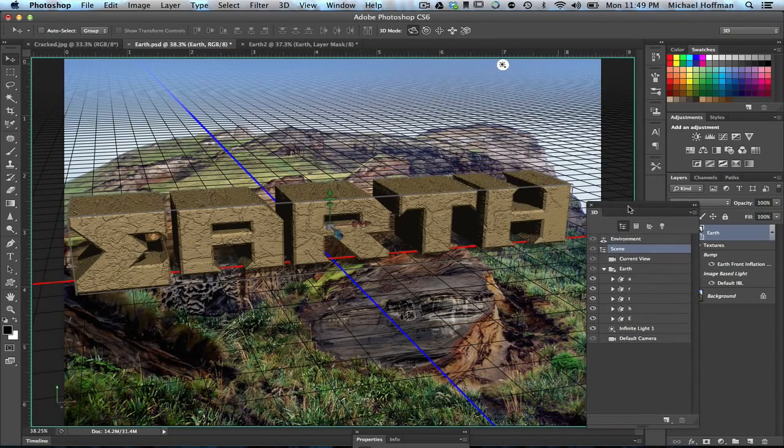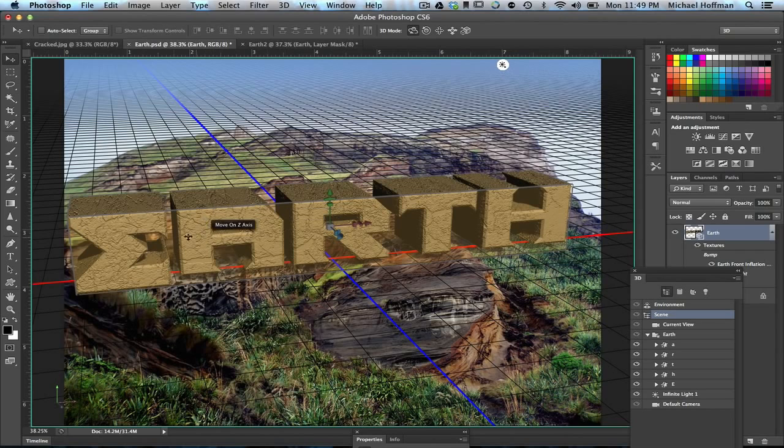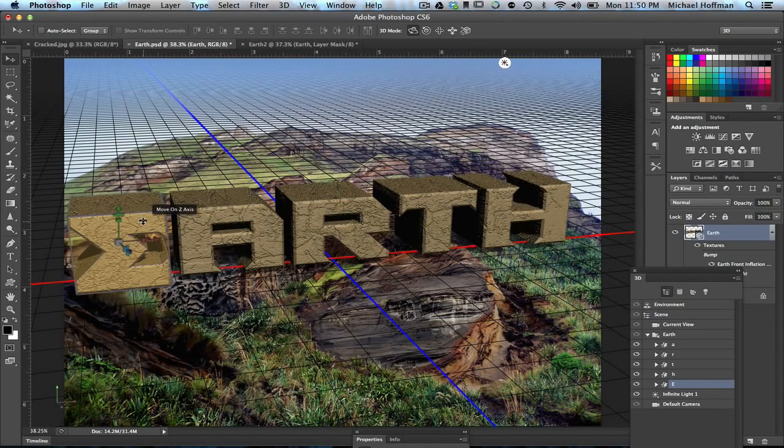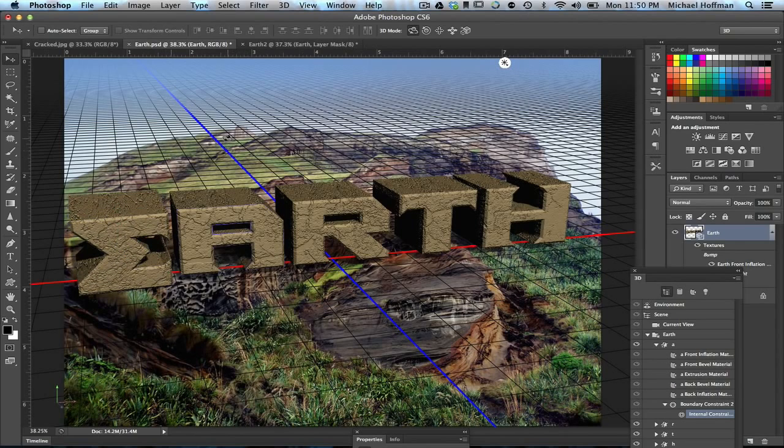So that means we can actually click on each individual one of these, and we can move it around independently of the others. So we'll just click, choose, and reposition and get these things set up the way that we'd like them to be. Don't forget that you can actually click on the axis tool to interact directly with the object, or you can click out here in space, and in that case you're using the capabilities of the move tool that you've got selected.